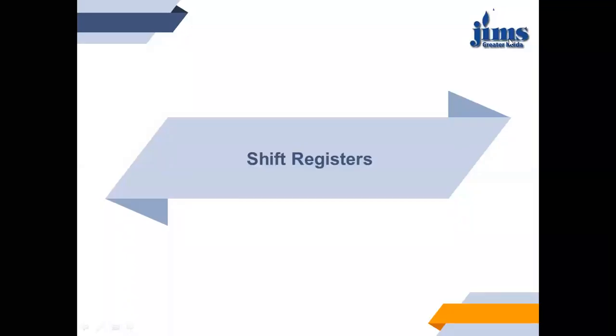So far in the last some classes, we have studied about flip-flops. In the basic, we have four types of flip-flops: D, SR flip-flop, JK flip-flop, and T flip-flop. The flip-flop in general is a single bit storage device which stores a single bit either in the form of zeros and ones. We have studied about different race around condition in the SR that has not allowed conditions.